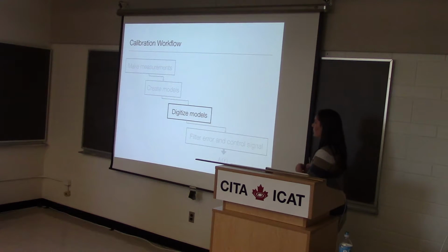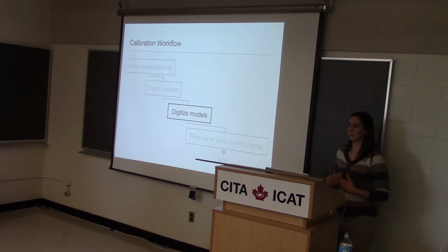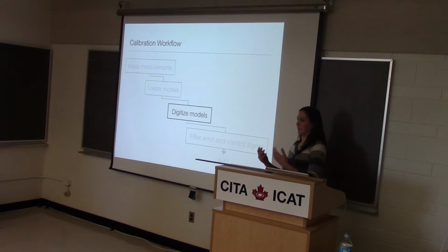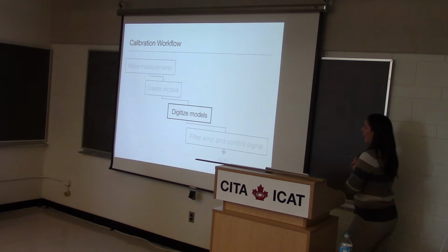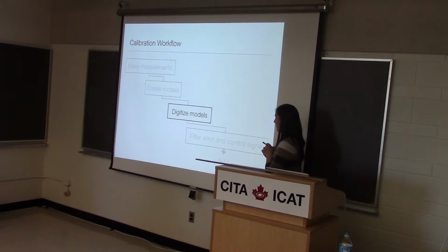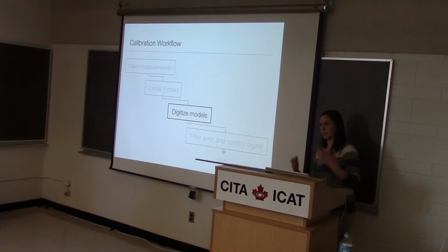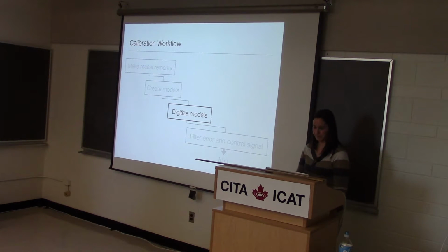In addition, we do calibration offline. We have always found the need to recalibrate our data with better accuracy, several times usually. And so for those offline recalibration runs, we would like to be able to parallelize the process as much as possible, taking full advantage of the LIGO clusters available to us. And to do so, you don't want to have the entire lock stretch necessary to get the right answer with an IIR filter. So we're going to use FIR filters.